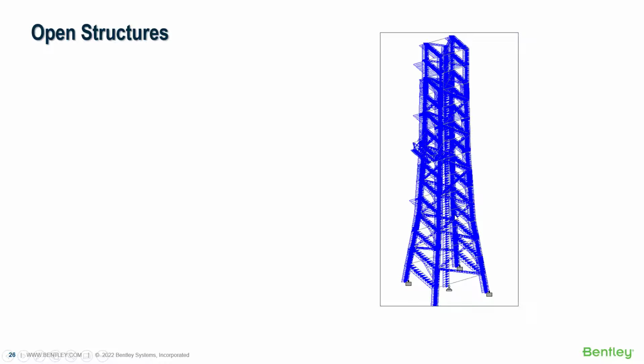For an open structure, the wind is directly applied on the structure. Here the load intensity will be based on the individual dimensions of the member. So here the program determines the width of the individual members and multiplies it by the wind pressure and distributes it as the UDL for the member. Please note that for open structure, all the members in the structure will be receiving the load, except for the members whose local x-axis is parallel to the direction of wind.